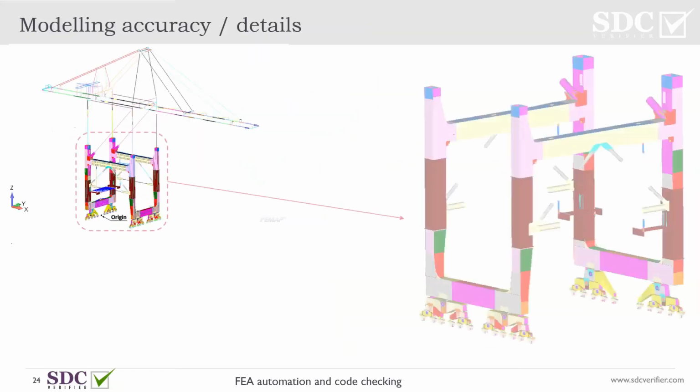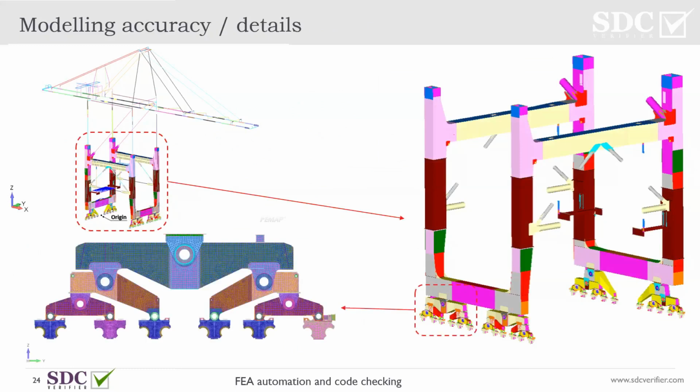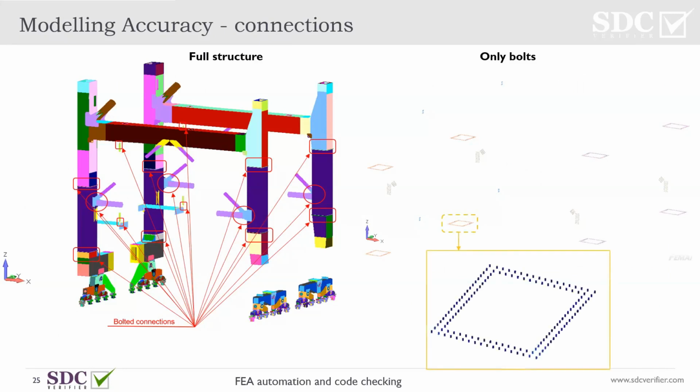So this is one more example. How should we care about the model? In some cases you need to model a large part of the structure, not only the connection, if we need to provide a high level of accuracy, including the gantry system, and of course it's not limited to the main steel structure, and we should care about the bolts as well. In our situation, we model all the bolts as well, because one thing is that their strength level might not be enough, which can potentially lead to failure. Another thing is that fatigue also exists in the bolts. So that's about the detailization.